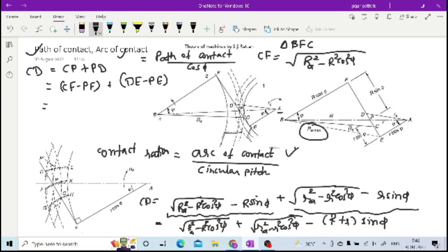From here to here, BE. Right now your addendum radius is BC. If you have your addendum radius as BE, then it will touch the base circle of your pinion, because here it is crossing the clearance you have provided, and it is meeting at the base circle if it is BE. Now if it is more than BE, then it will start penetrating into your pinion. That is known as interference.